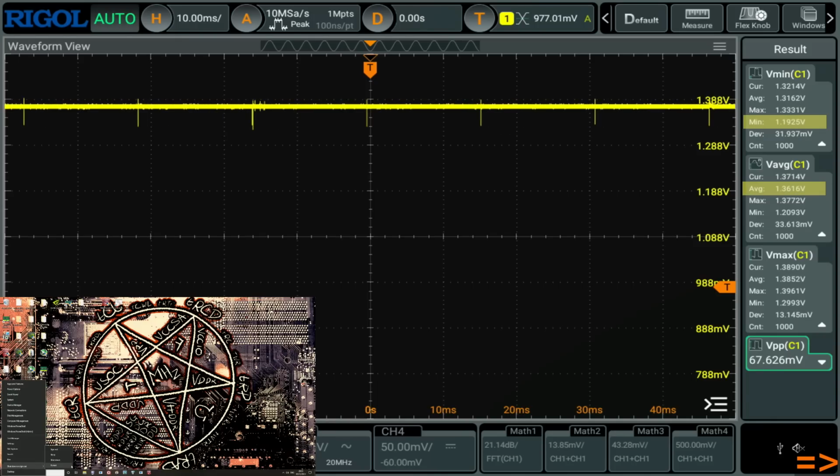That would totally throw off your results. If you're trying to test the power delivery capabilities of the VRM, you don't want the average voltage moving around. But if you're trying to get the best overclock out of your CPU, you don't want terrible voltage regulation. So there is a good reason for boards to have a 0 V-droop LLC.